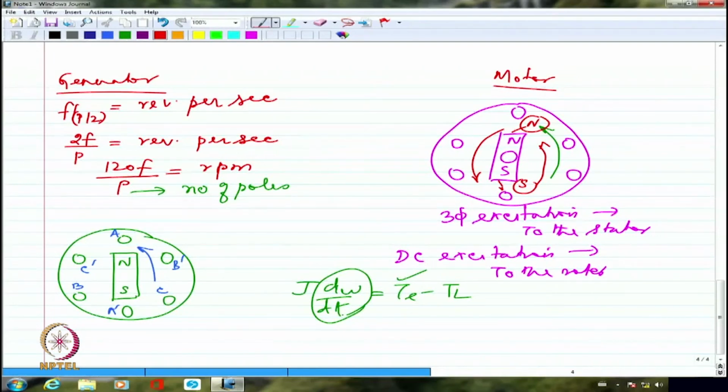If I start with 0.5 hertz, then 1 hertz, then 1.5, 2, 2.5. If I go slow, then I give the rotor enough time to catch up with the stator revolving magnetic field. So if I have variable frequency starting with 0.25 hertz, 0.5 hertz, 1 hertz, 1.5 hertz and so on, I will be able to make the rotor catch up with the stator revolving magnetic field speed.